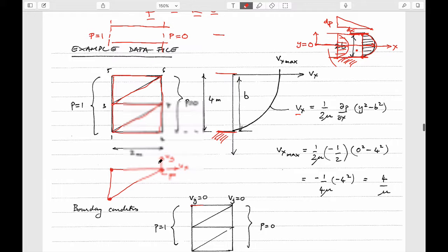And we need to figure out what the boundary conditions would be in terms of these other components. This would be a boundary. We're representing half geometry, just to make life easy for us. So this bottom boundary is closed. So we know that the velocity in the y direction has to equal 0 across here, right? By definition. This, if you like, is a line of symmetry. Actually, all of these are lines of symmetry. But we only have to impose this top one.